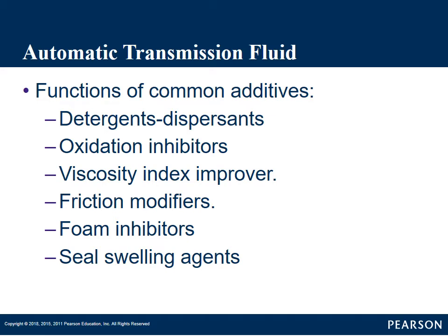When we're talking about a hydraulic circuit, and those of you who've had brakes understand this, anybody that's had brakes that have a mushy brake pedal, that's because you may have air in the system. Air compresses. Fluid does not like to compress, okay? So if we get air in a transmission fluid, it's going to compress, we're going to have shifting problems, or we're going to damage the transmission.